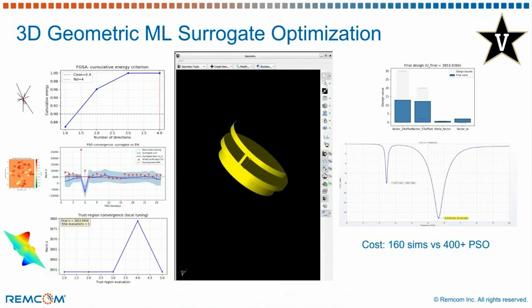Looking at the latest research in this space is surrogate modeling with fast global search optimizations, married with particle swarm optimization, and developing trust region techniques. So this is the next generation of trust region, particle swarm techniques, apologies, not physical optics, looking at the creation and the optimization of a 3D antenna.